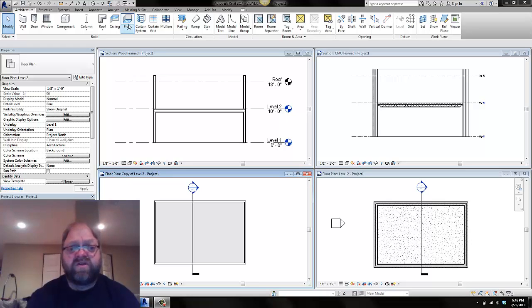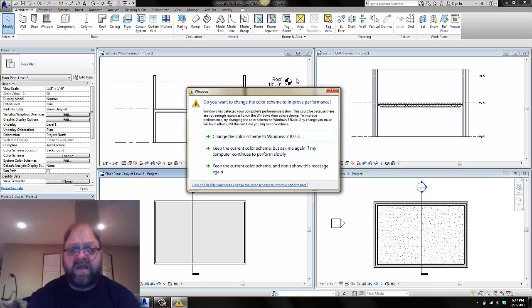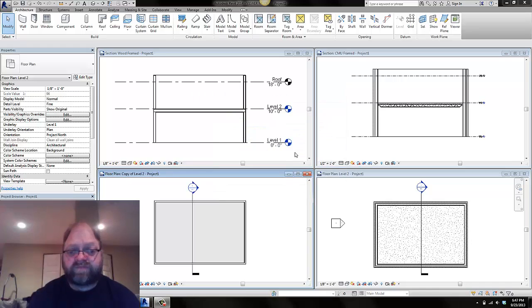But in essence, a floor and a ceiling and a roof are all kind of the same kinds of objects. They're slabs of stuff that we put in space. So in a generic modeler, it might just be called an extrusion, and you would draw the shape and extrude it. A roof is a little bit different and has slanted faces, but maybe you would do an extrusion and cut some pieces off of it. But anyhow, we have specific tools that are used for the modeling within Revit.